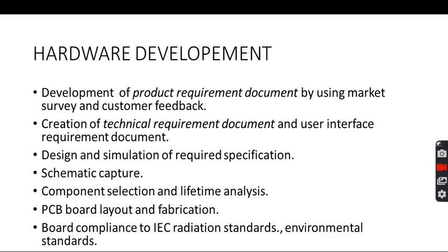So hardware development, I have already told you, both software and hardware will be there. In hardware, I have told you the schematic capture. Before schematic capture, you have to create the simulation and check whether the schematic is working, and then you have to go for component selection. Lifetime analysis is one of the things. When you are giving a product, a particular IC, it has to work for at least some 10 years. When it comes to defense, it will be more than that, maybe around 20 years they will give for the lifetime analysis.